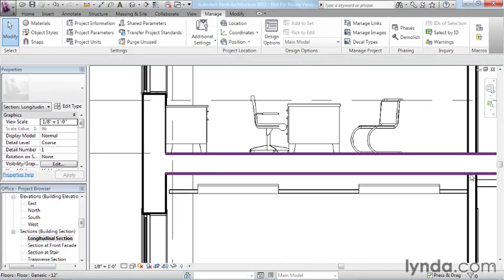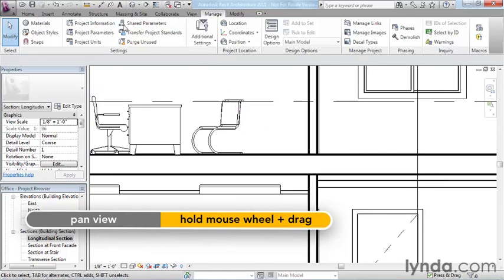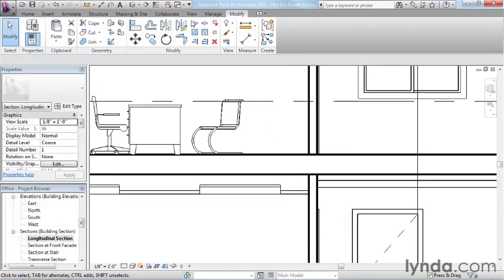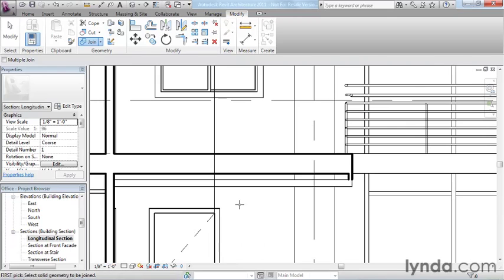Now over here, we're still getting a heavy line here and here. You can actually start fine-tuning some of that if you like by going to Modify and using the Join tool, and you can just join geometry to one another, and it will actually start to clean up those intersections for you. So if you want to make this a little bit more of a presentation type drawing where everything just has one overall profile, you can certainly do that. Now, if I continue to scroll over here, this is a ceiling, and this little tiny item here is actually a soffit wall.